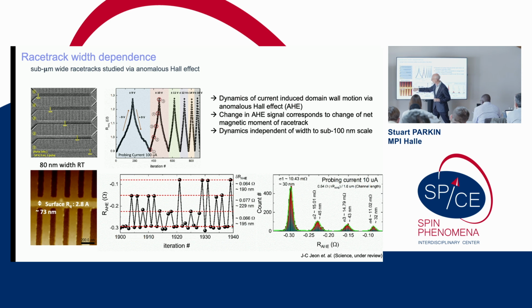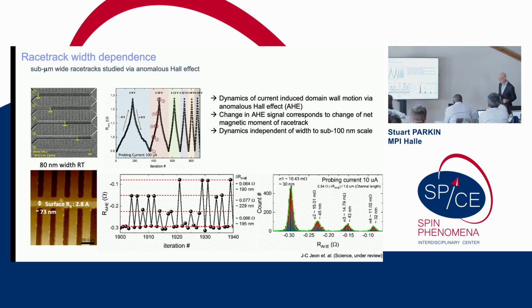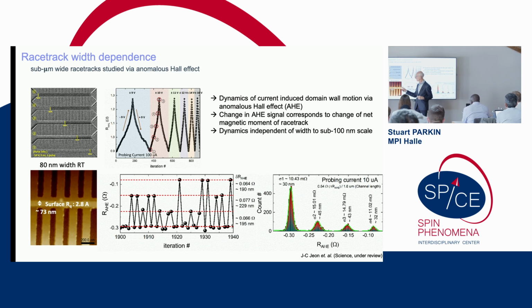And the platinum layer underneath is slightly wider, and we have platinum electrodes. So we can measure the anomalous Hall signal. But by engineering the shape of this platinum wings, we can actually use the anomalous Hall signal generated at this electrode to detect the domain wall up to 20 times further away. It depends on the details and the engineering of this patterned platinum underlayer.